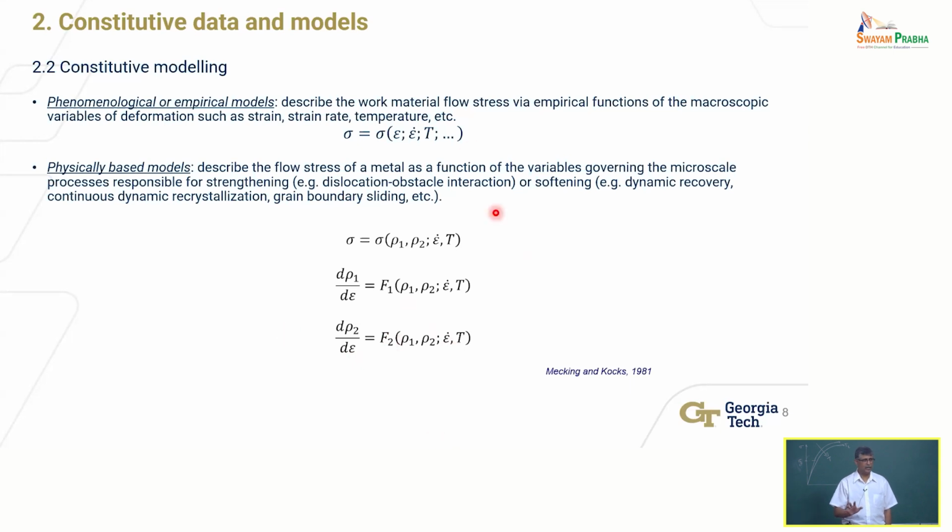It's a much more complicated model for sure, right? This allows me to say something about things like grain size, etc. What will happen after machining to the grain size? As an approximation, the stress is related to the dislocation density of the material in some sense. Rho is the dislocation density, okay?